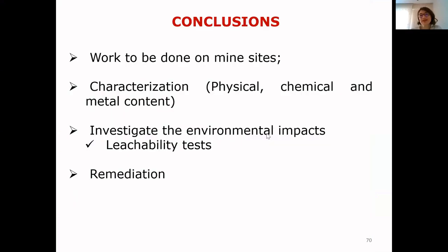So in this study, we learned that we need to characterize the mine sites. For this, we should define the physical and chemical properties and also the metal content in the material. Then we should investigate the environmental impacts. For this, we can do leachability tests.